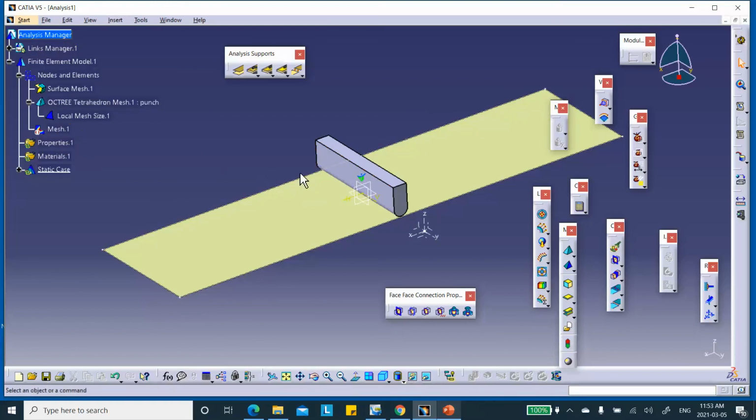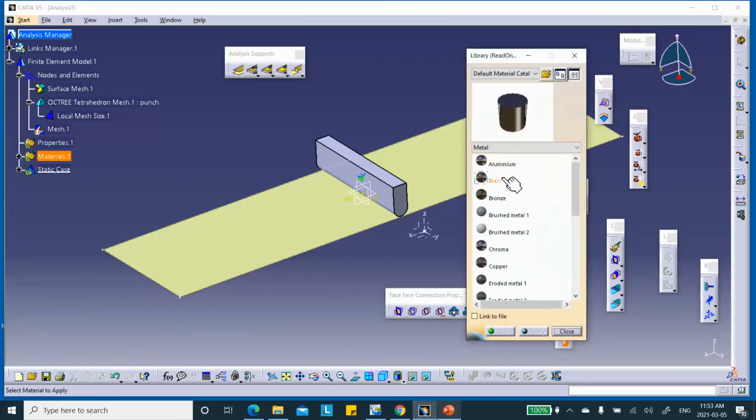But because of the way I did it, I first went to the advanced meshing tool, and I had to do this thing myself. Notice that there is no property associated with it, okay? So the different ways of doing it, one is you create a user. First of all, you create a material here, and it was steel, right? Steel, user material, steel.